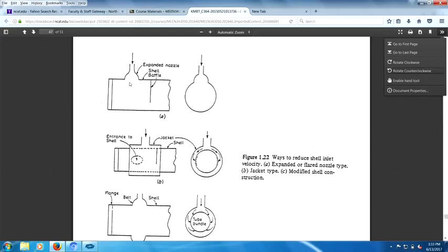So I'm very much sensitive to what velocities are coming in to hit my tubes, because that could set up a whole bunch of tube vibrations going on. So a number of things I probably want to do is make sure the expansion bellows is large enough to let the flow in. You can have a belt. Is this what they call that? A jacket. I call it a belt. Ah, down here's a belt. Okay, gotcha. This is more of a belt here.